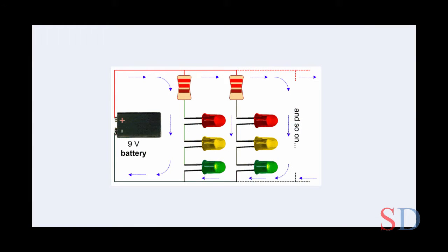Now theoretically, if you're working with direct current such as a battery, you don't really need much of a circuit. This is a 9-volt battery. My circuits are 12 volt, and you can size your diodes depending on the total resistance and the voltage across the circuit. By adding up the voltage of each diode, you can directly hardwire a diode set. Say you had a set of diodes that added up to 9 volts for this battery, you wouldn't need a resistor.